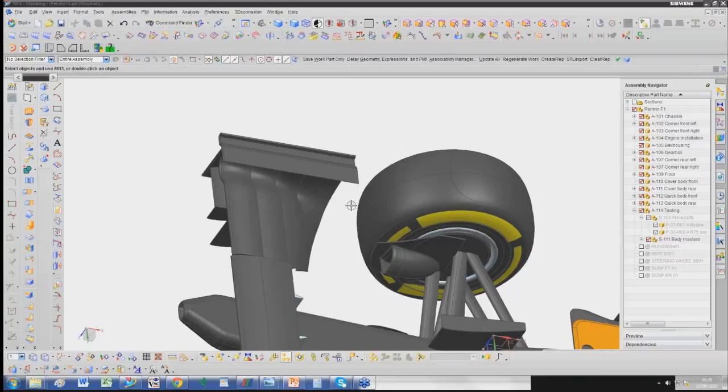And I have to say, this is the key to everything. This is the key to understanding how to improve the design and know what next step you want to take on the design. So look at both. Dynamic pressure, you have to look at it in the field, in the flow, okay? Static pressure on the car surface. This is normally how we look at it.